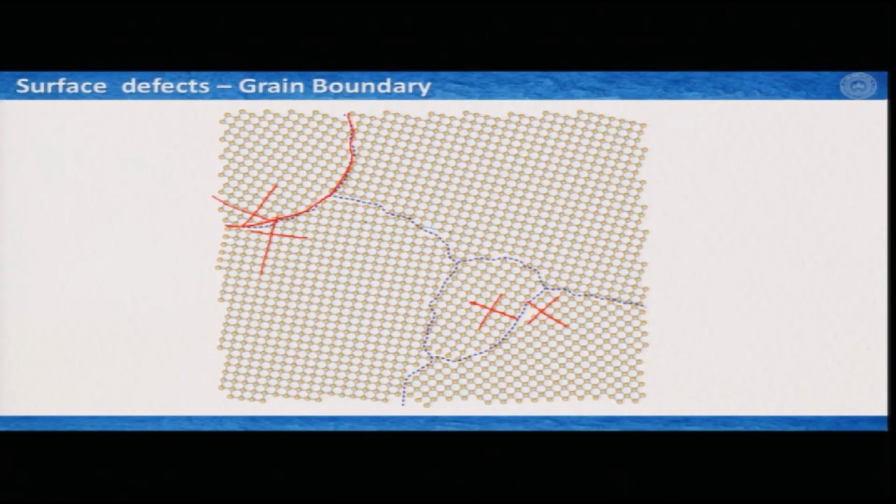Now this grain, as it appears here, for example if I consider these grains, is extremely homogeneous. There is no dislocation inside this area, there is no vacancy inside, there is nothing. So it is perfect, but that is not always the case. So this individual grain can also be deformed, it may also have some sort of subgrains and so on, and therefore we see different kinds of features. For example, undulose extinction in quartz, we will learn more about it soon.